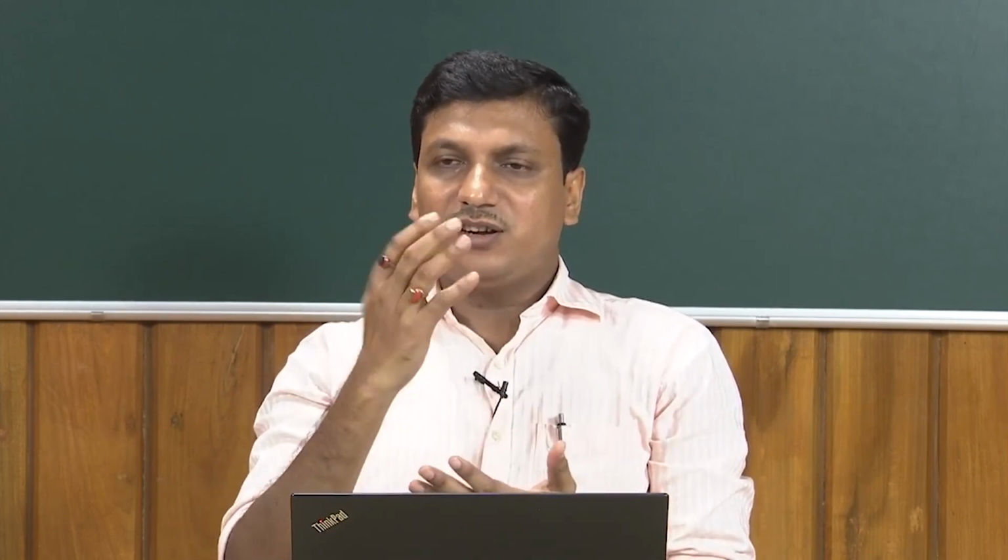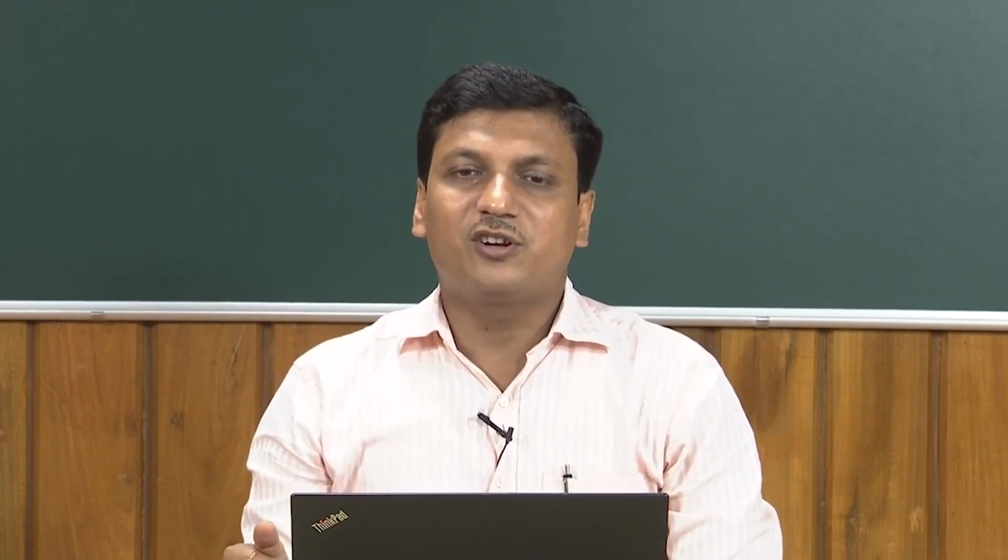So over the surface it is circular, but in the depth direction, in the x z plane, it can be like an ellipse. Therefore, in case of spot welding, if the heat intensity is very high, we can use the ellipsoidal heat source model. This is one kind of volumetric heat source model.